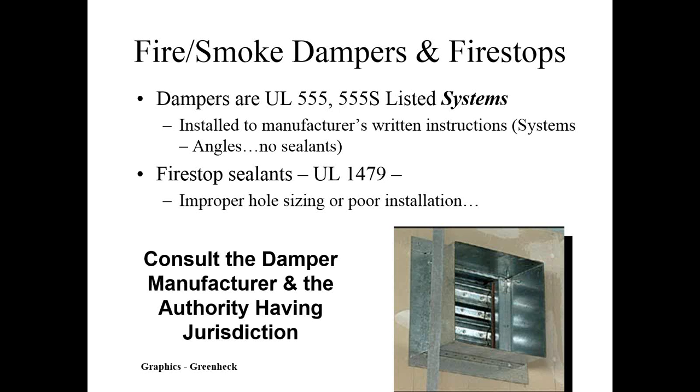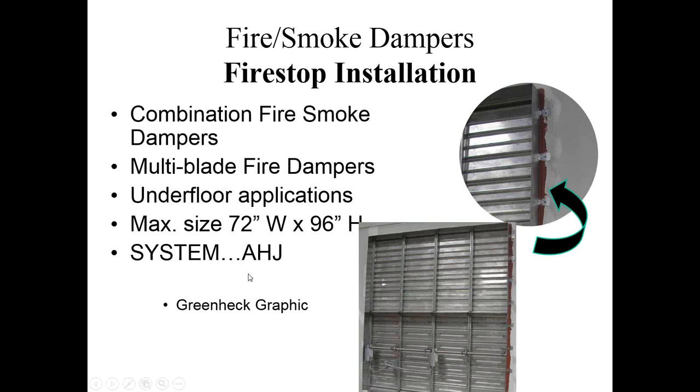Firestop sealants, it was believed, could not be used in the angular space behind these angles because it was thought that the louvers wouldn't be able to turn, because as the intumescent sealant expanded behind this angle, it might restrict the movement of those louvers inside the damper and cause the fire damper not to work. Testing has proved that it can be used, but you have to consult the manufacturer and the authority having jurisdiction to be sure that Firestop sealants can be used in many different places on fire dampers.